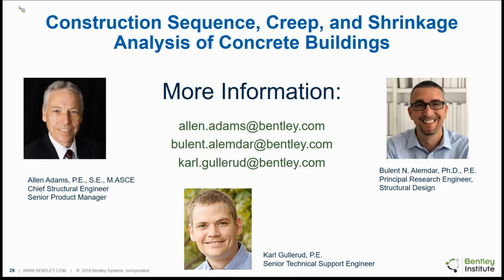And that's often the case. Ideally, we would size those end columns to be smaller because the gravity load is smaller. But those are precisely the columns that take the bulk of the wind and seismic forces, and so they need to be bigger. And so it's very often the case that the end columns and the interior columns are the same size because of wind and seismic force requirements.